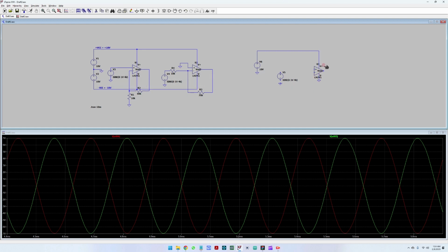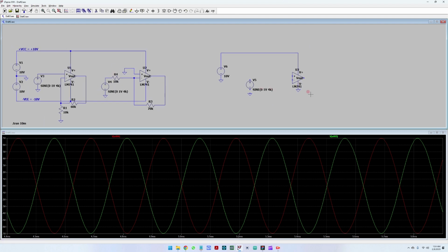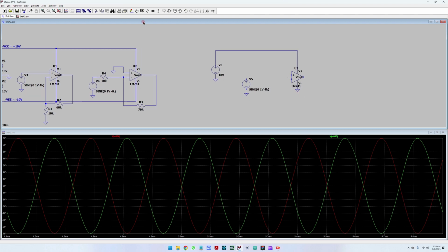And so this is great. One other thing that we have to do, so we've connected this. Let's connect the supply. Now, one thing that is quite important here is, if we connect this to the input, you will see only half of the wave. Usually it's good to have an isolation between the input signal and the input into your operational amplifier.